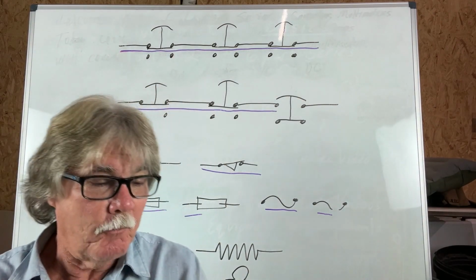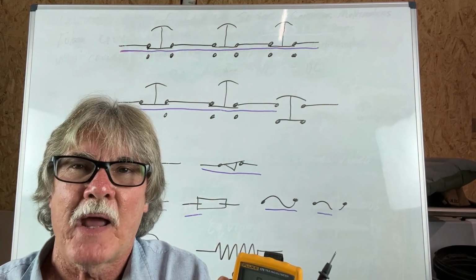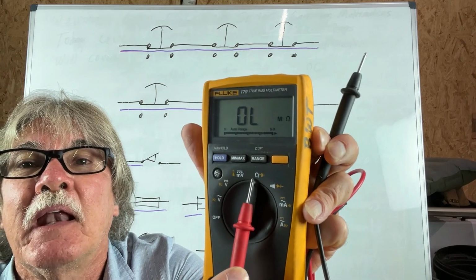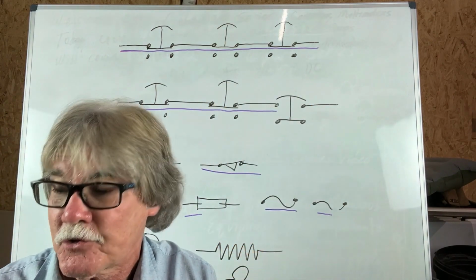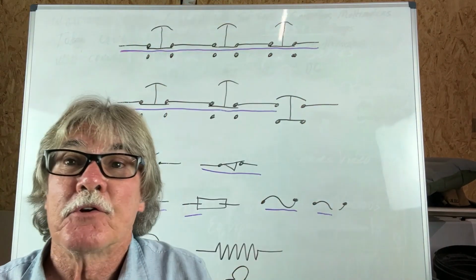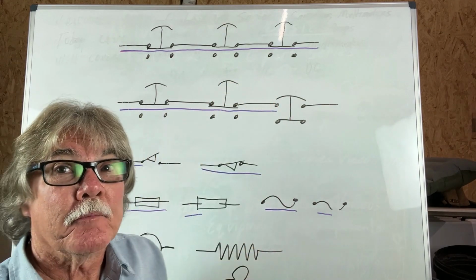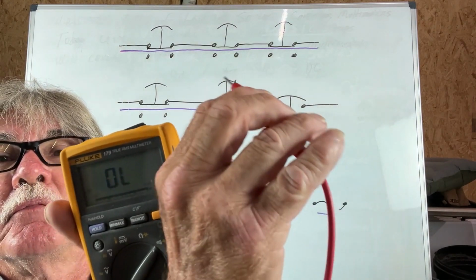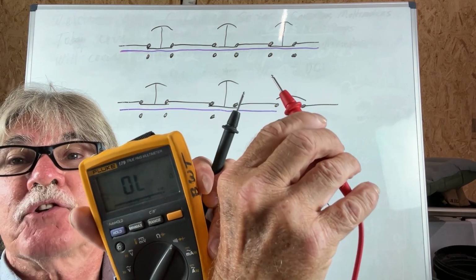When you're troubleshooting components or a circuit to find bad connections, you will want to set it to ohms and then read the reading to see what it is. When you've got it set to the beeper, you're really just checking to make sure that you have a path and that you haven't got an open. So basically, there's a closed and there's an open.